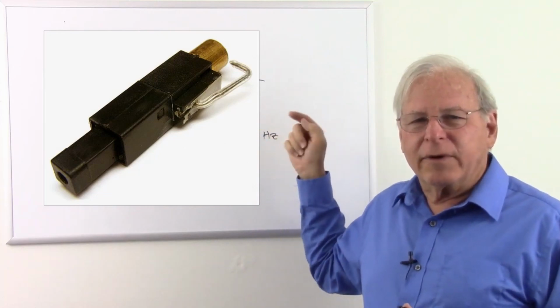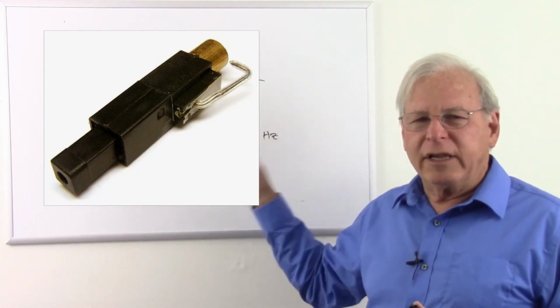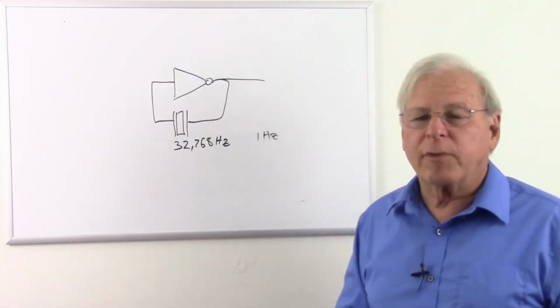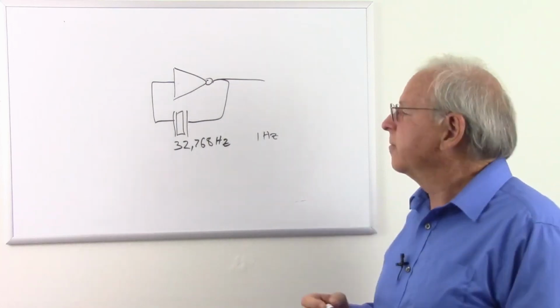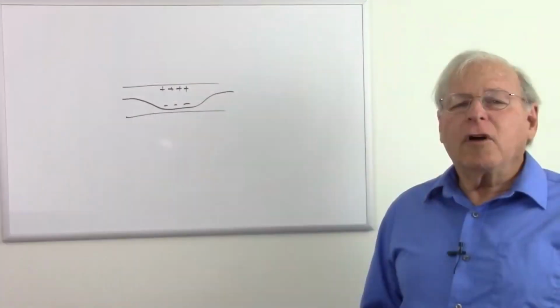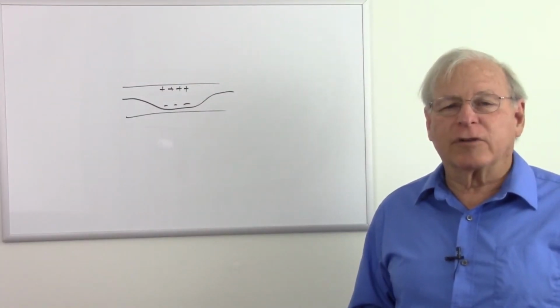Press on the button here with a device and it cocks a hammer, and at a certain point it releases it. That hits a crystal and creates thousands of volts, enough to make a little spark to light a cigarette lighter or a camp stove or something else. So those are the places we see crystals. So those are some components that need to be talked about, but just didn't fit anywhere else in the course.